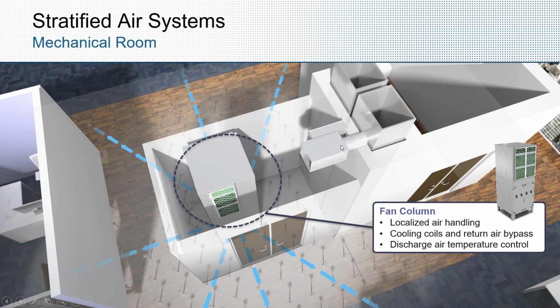And typically you can put a single duct box here and a damper that controls your outside air to the mechanical closet. And so that can be used to either open or close the amount of fresh air that's being provided to the space. And that can just simply dump into the mechanical room and be pulled into the air tower and mixed with the return air and can be essentially filtered or other clean air technologies kind of integrated into this vertical air tower to then mix and provide that clean air down into the raised access floor.